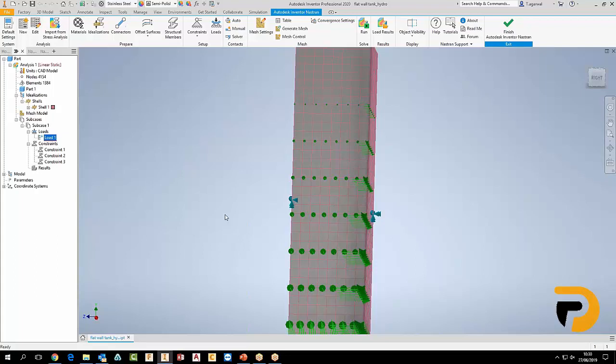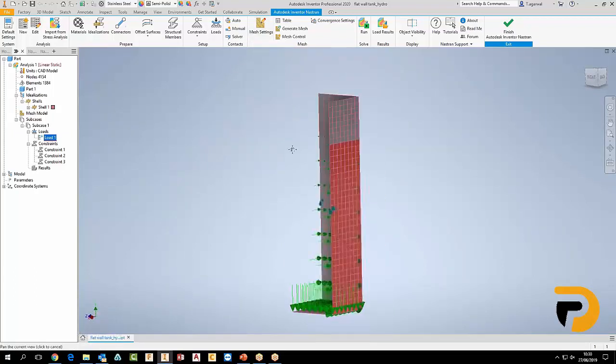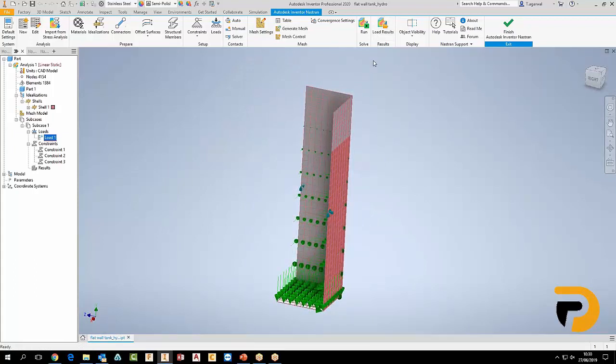Or what you can do is start with a coarse mesh and less accurate results, and as you go on, you can see how much the result is improving by refining the mesh every time. Correct. And if it's not changing much, you can stop refining the mesh at that moment because the results are already accurate and won't get more accurate any further. So yeah, there is a mesh convergence study that you need to do before you run the model.